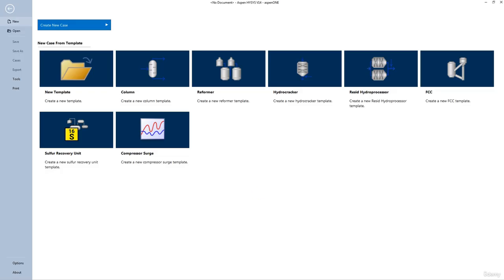Task 1. Define the properties environment. When natural gas is cooled to a temperature of approximately minus 160 degrees centigrade at atmospheric pressure, it condenses to a liquid called LNG. Natural gas is composed primarily of methane, typically more than 70%, as well as ethane, propane, and other hydrocarbons. Impurities such as nitrogen, oxygen, carbon dioxide, sulfur compounds, and water are also present.